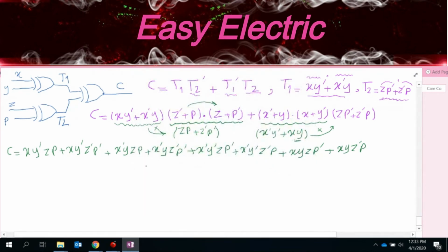because we want to get the truth table. Okay, so I start with this, you help me. What should these minterm numbers be? M, you tell me the numbers. So this is definitely 1, this is 2, this is 4, this is 8. So what should be the number for the first one? You could just type in the chat box what the number should be. M11, that's right. It should be 8 plus 2 plus 1, which is 11. Definitely right. How about this? Type it for me. That is actually 8.